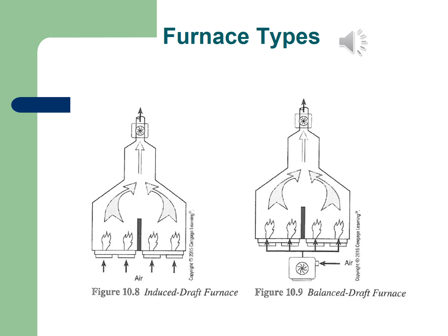Also, for example, if the forced draft fan that's at the bottom is maybe, say for instance, letting in more air than is actually removed by the induced draft fan, this can cause a buildup of pressure inside the furnace itself, and that could also be dangerous.